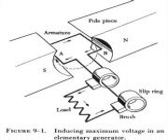The neutral plane is the position where the plane of the two opposite coils is perpendicular to the magnetic field in the generator. On a few generators, the brushes can be shifted manually ahead of the normal neutral plane to the neutral plane caused by field distortion. On non-adjustable brush generators, the manufacturer sets the brushes for minimum sparking.